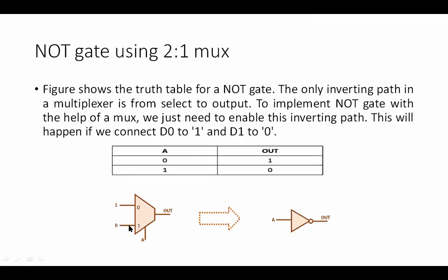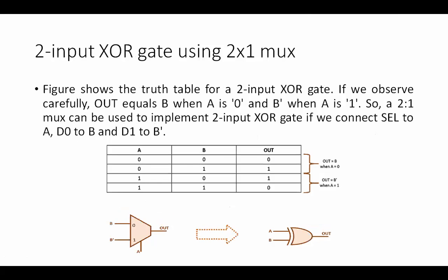So in this way, Mux plays a very important role in implementing any kind of circuitry. We can even take this to the next level by creating a different truth table, trying to find out the relationship between the outputs and the inputs, and trying to come up with statements. These statements can be mapped onto the multiplexer.